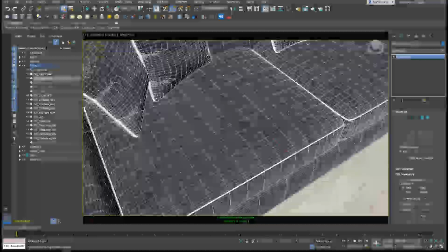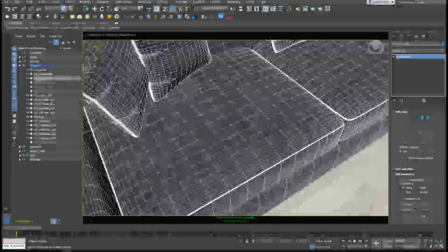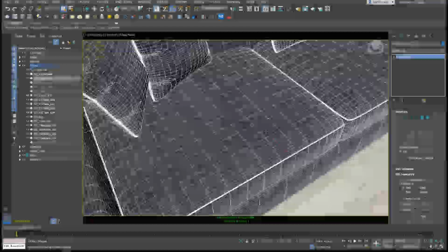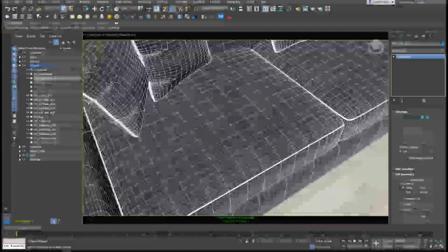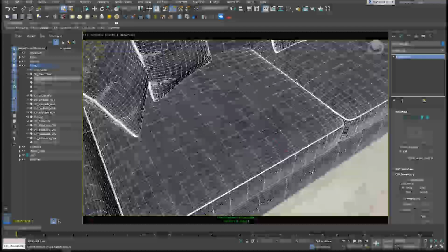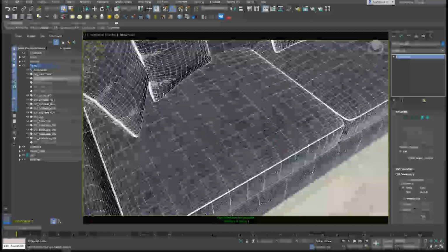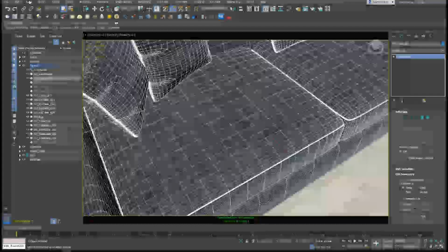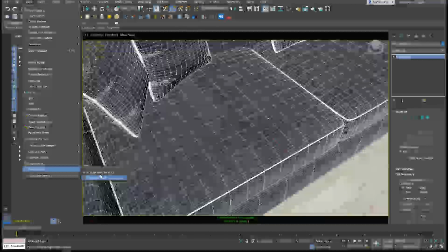Now, obviously you want to avoid things like overlapping faces, which can cause Z-fighting, and you want to avoid T-junctions. Basically, anything that looks bad in your 3D tool, whether it's Max or Maya or Blender, that's going to look bad in Unreal too. So be sure to clean that stuff up using your basic mesh cleaning tools. I know with 3ds Max, you have the Mesh Inspector, which will automatically look for these kinds of errors.